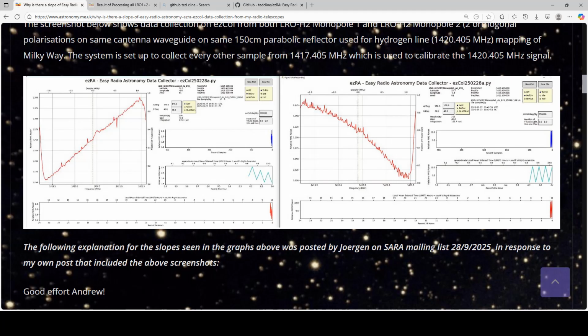So what I'm doing here is, after some discussion with Ted and Jason and other people, I decided it might be worth having a go at something. Inside the container there's a monopole, which is, as Adrian said, slightly less than a quarter wavelength. You cut them slightly longer than the quarter wavelength, put it inside the dish, and then you measure the output while slowly trimming tiny bits off the end until you get your maximum performance using your NanoVNA, because it is a slightly different length within the container than it is in free space. Once you've got that about right, that's what I ended up with on one of my signals.